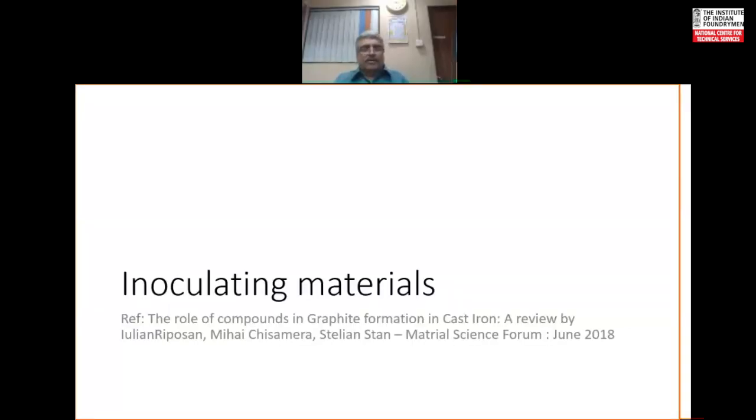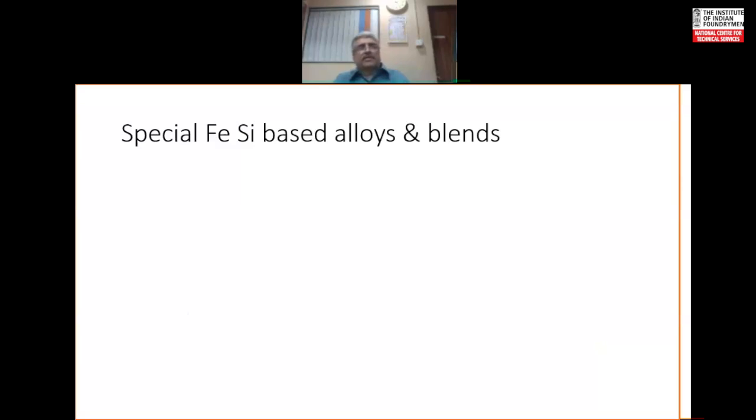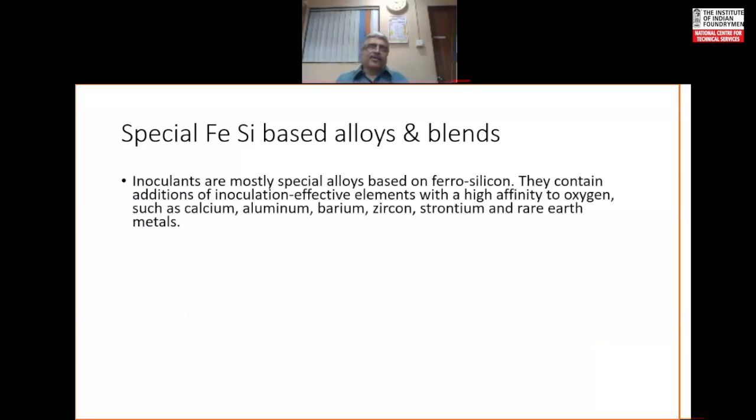Now let's look at what are the inoculating materials, and the content that follows I have picked up from an excellent review paper published in Material Science Forum in June 2018. The title is The Role of Compounds in Graphite Formation in Cast Irons. It's an excellent paper. Generally, special ferrosilicon based alloys and sometimes blends, in the past at least, were used as inoculating materials.